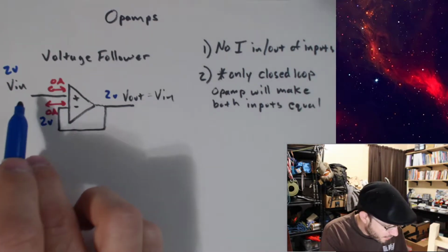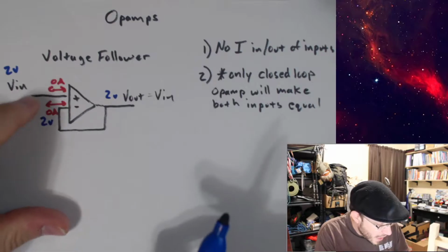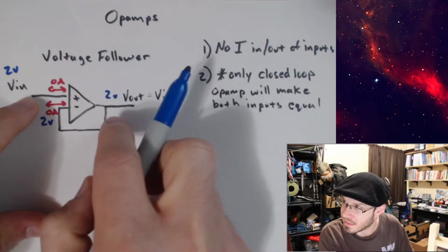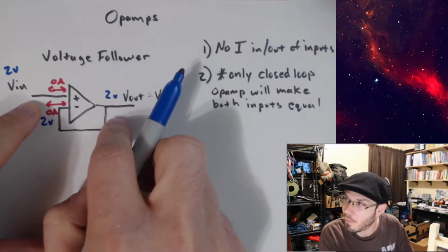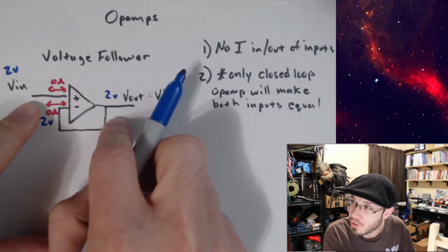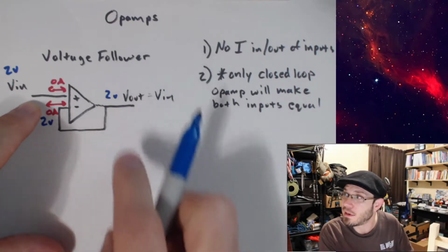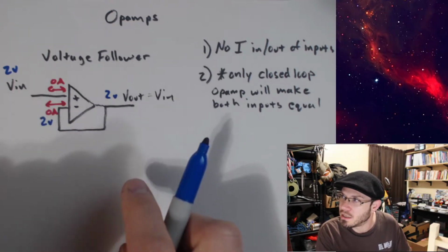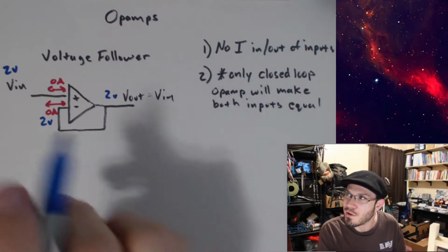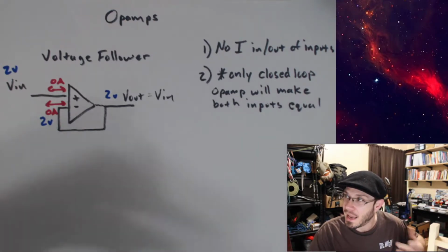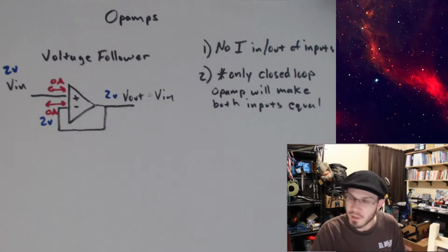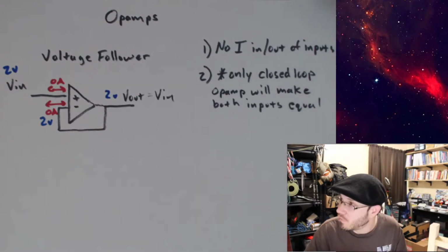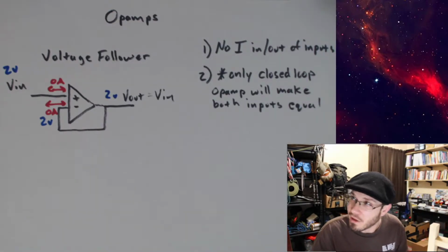If I need to measure a voltage and I don't want to be hindered by the impedances, just like when we were looking at that common emitter amplifier and you solved for your input impedance and output impedance, then used the generic amplifier model, and then saw that voltage divider. We don't have to worry about that anymore. You don't have to calculate the attenuation, the signal drop, the voltage drop that you get by virtue of having, say, a medium impedance driving a medium impedance.